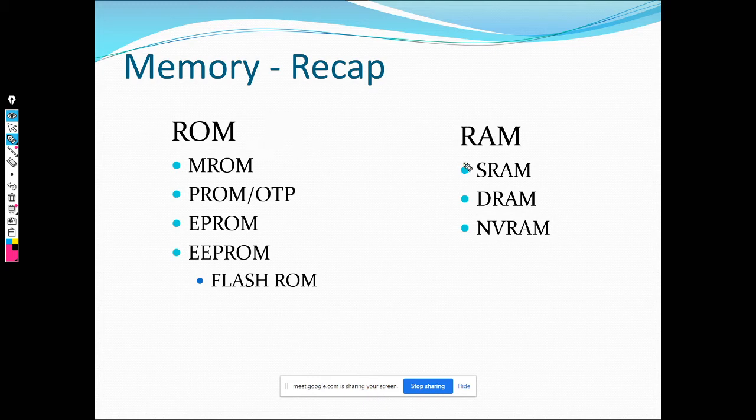Next we come to RAMs. We have SRAM and DRAM, the two main categories. SRAM, as we saw in the earlier class, is made up of 6 to 8 transistors. It's very fast because everything is transistors, one of the fastest memories available, next to the flip flops. The downside is that it's very expensive to fabricate and very power consuming. By the way, caches are examples of SRAMs. Beyond the cache, we are not using SRAMs anywhere else.